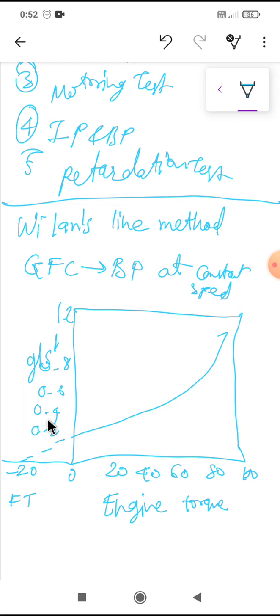In the diesel engine, we draw a constant volume of air for compression and vary the fuel injected, and technically we alter the quality of the air-fuel mixture. This is called qualitative governing.